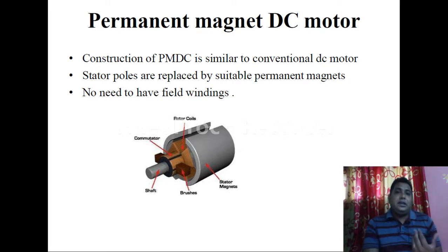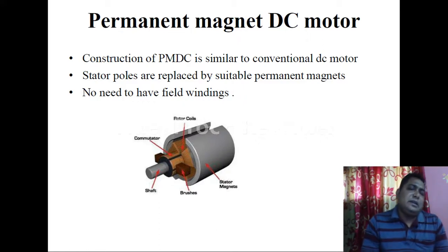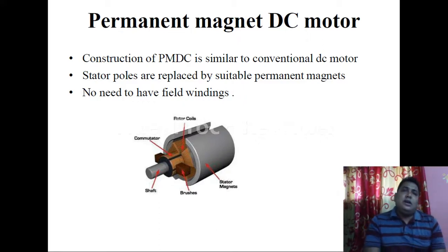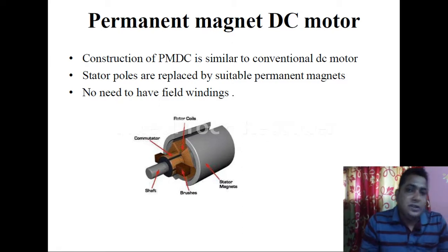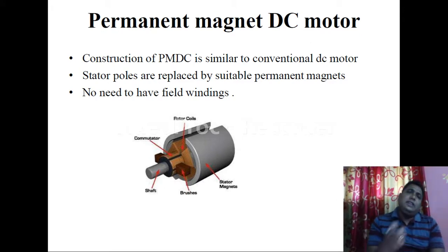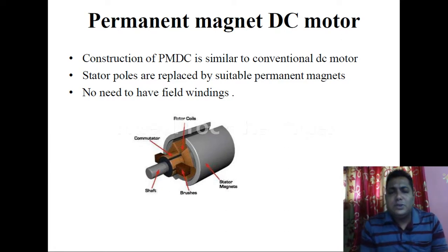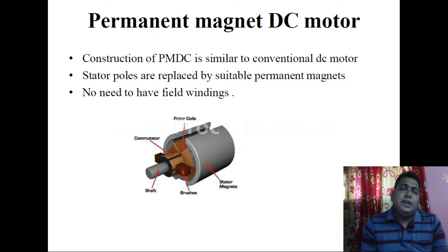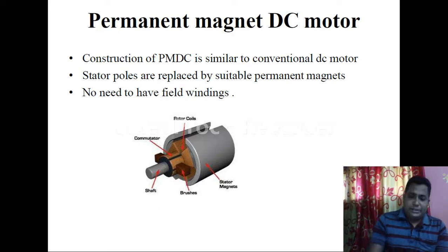The point is, if we think of a large machine, then we have to think of the industrial section. Whatever permanent magnets are used there are large in size, and we know that a large permanent magnet has a very high cost, and with long term use the strength of its magnetic field reduces. Those are the different issues. That's why we are not using permanent magnets in those cases. For small machines, we actually use the permanent magnet.